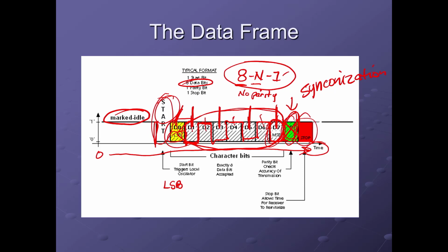So basically, as an example, if we're moving Modbus data over an asynchronous serial data link, the Modbus protocol itself has something called a CRC data error detection code embedded right in the data. So it doesn't make any sense to be using parity in the connection, because the protocols that are being operated by each terminal are detecting errors in that way. So you'll see all connections now are no parity.